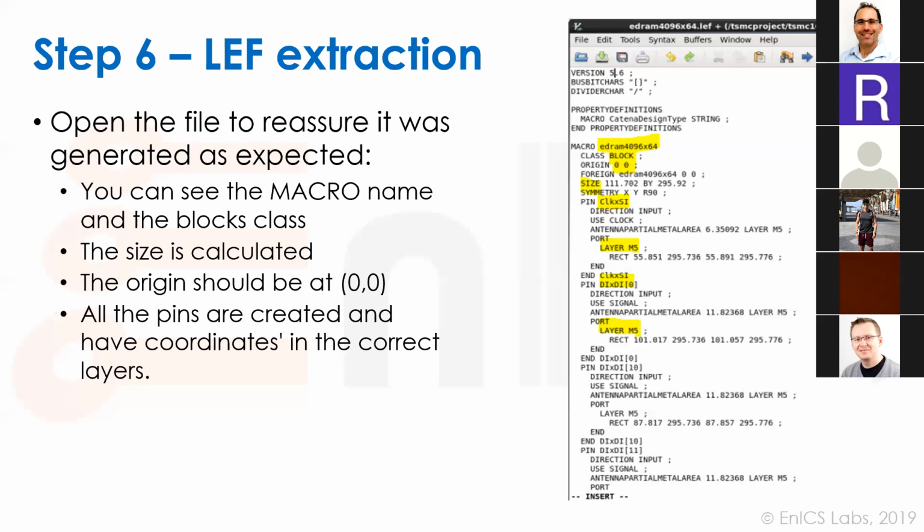if you actually design a custom circuit that needs to be part of timing paths, you need to integrate it and then create timing arcs with the higher levels. Then do you do it manually? I know that, unfortunately, in a lot of cases, and this is again speaking to Anatoly, that is still done manually for most analog blocks, trying to be by design as high margin as possible.